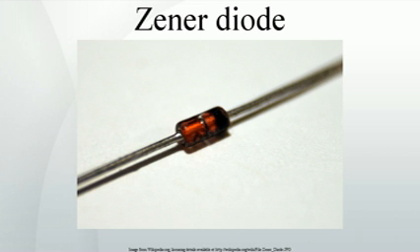The NPN transistor structure can be employed as a surface Zener diode, with collector and emitter connected together as its cathode and base region as anode. In this approach the base doping profile usually narrows towards the surface, creating a region with intensified electric field where the avalanche breakdown occurs. The hot carriers produced by acceleration in the intense field sometimes shoot into the oxide layer above the junction and become trapped there.